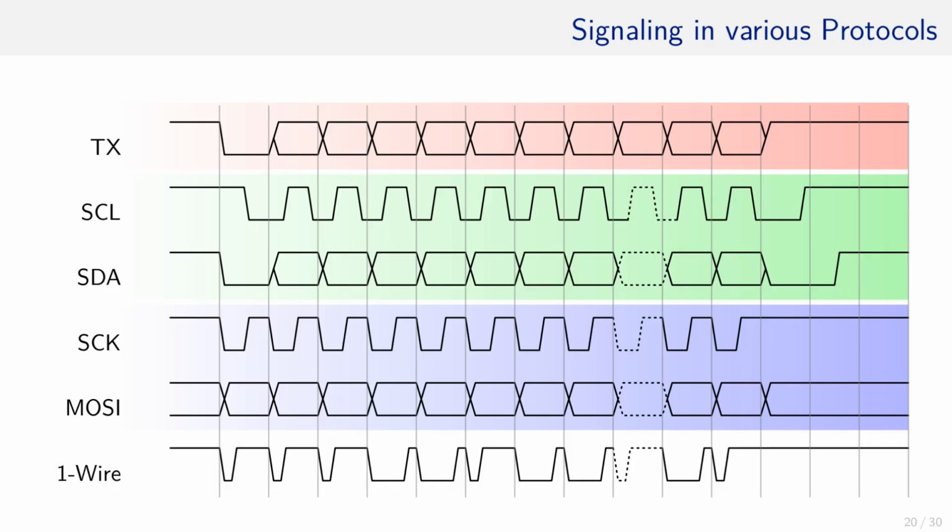The second observation is that most protocols have a wire dedicated to the clock. Even UART has it when the USART is considered. At one point in time, the data transfer starts. Interestingly, except SPI, all protocols start with a 0 on the data line. In I2C, we have the start condition, and in UART, the start bit. And the last important observation is that all protocols are serial and transmit the bits one by one through some kind of shifting the value in a register mechanism.